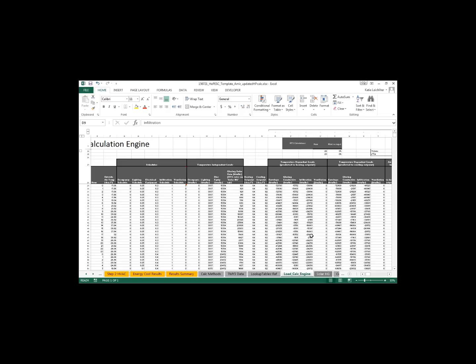To add a little bit on that, from my experience, this is extremely effective really early on in schematic design to do what-if scenarios. There will be default code U values in there, and then you might say, well, what if I double that U value?